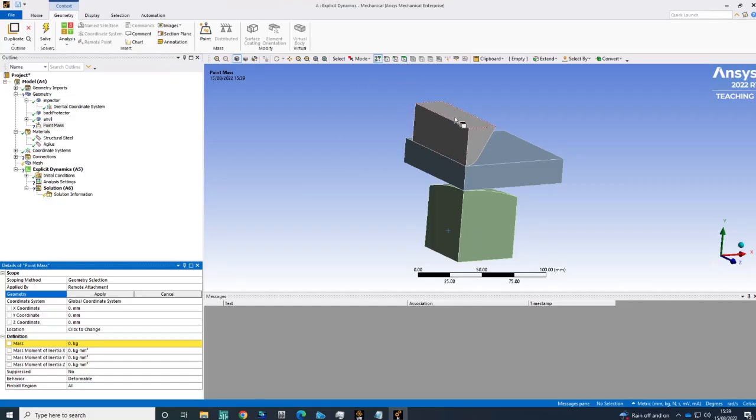So I believe I can use this place, and here there are the coordinates of the concentrated mass. I'm not too worried about this because I'm going to constrain this anvil to move along the y direction only, and the only parameter I need to define here is the mass, which is 0.943, and that is accurate enough in terms of kilogram.